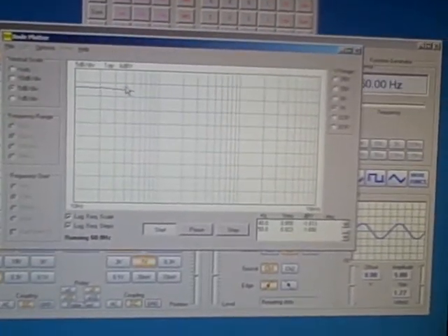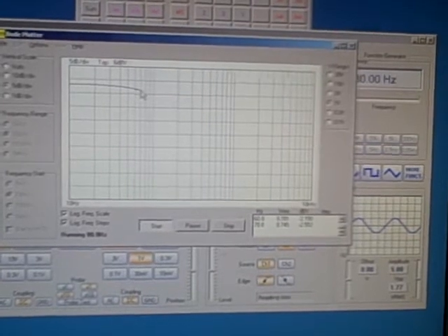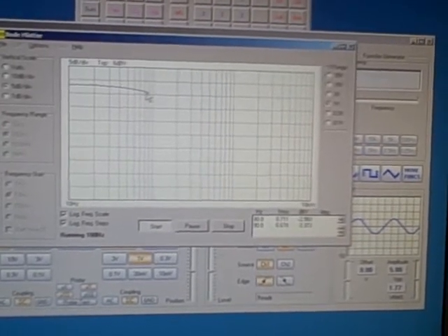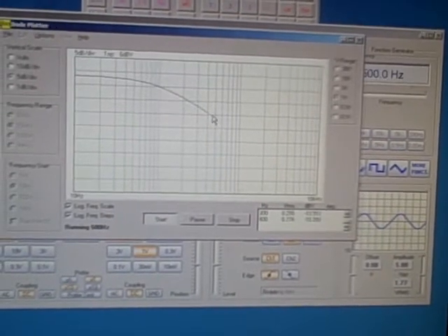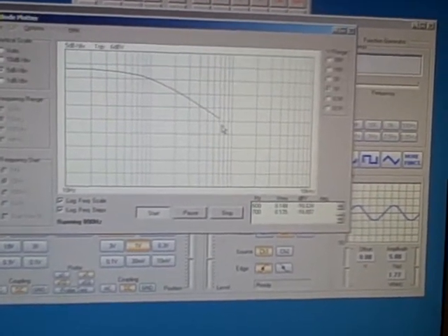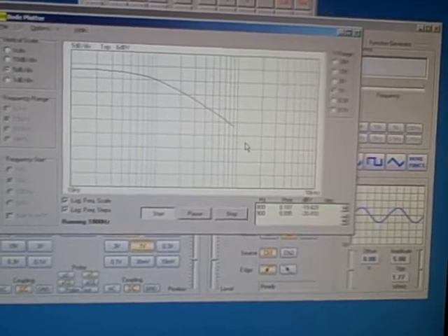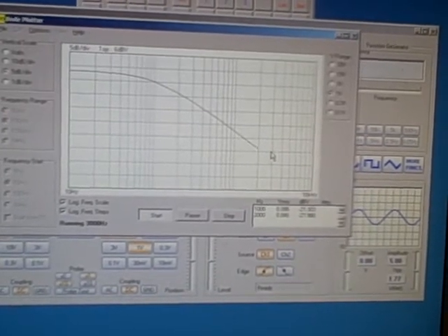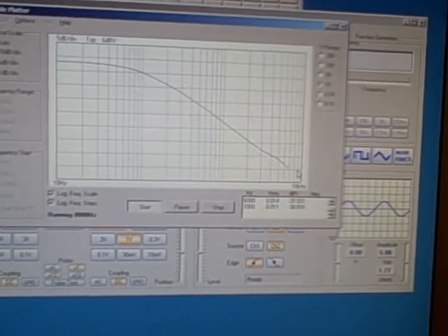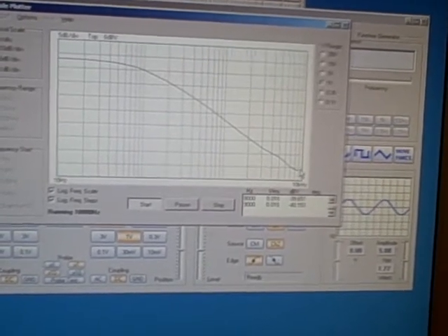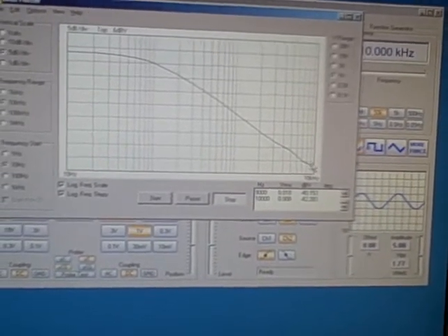So you can see starting off, it does pretty well, and then it drops as the frequency goes up. Right now we're at 100 Hertz, and as you keep increasing the frequency, the signal that you get out at the end goes lower and lower as the capacitor shorts more and more of the electricity to ground at higher frequencies.